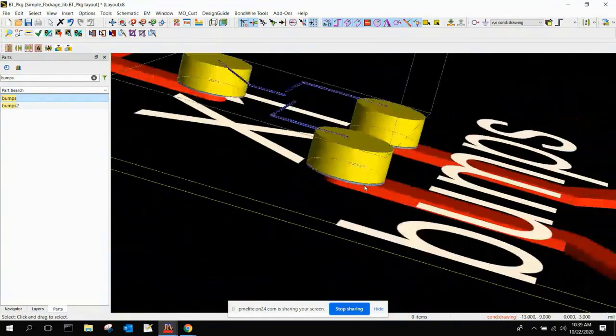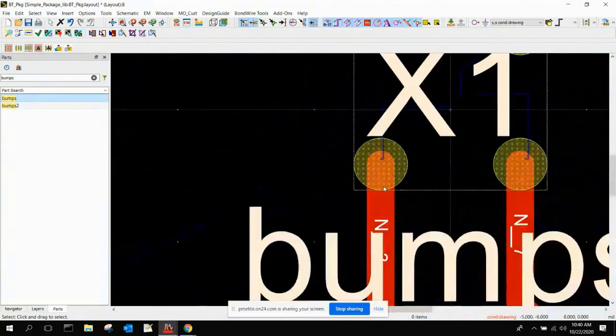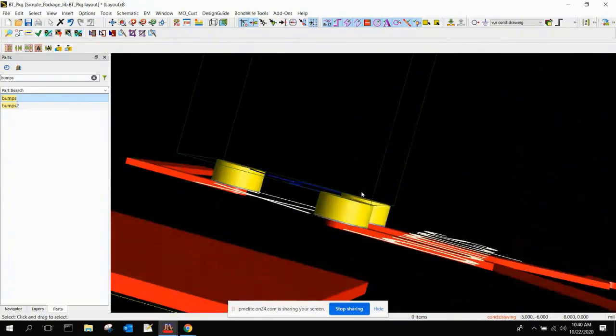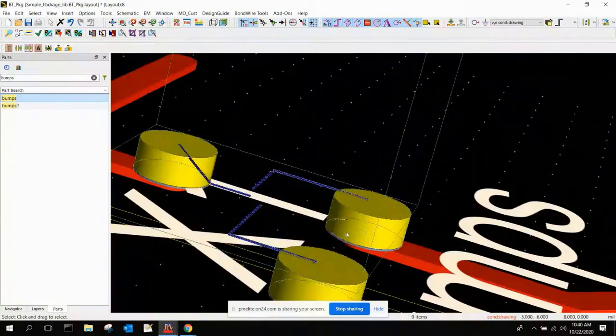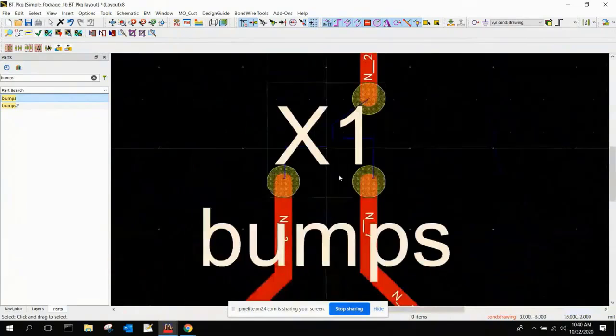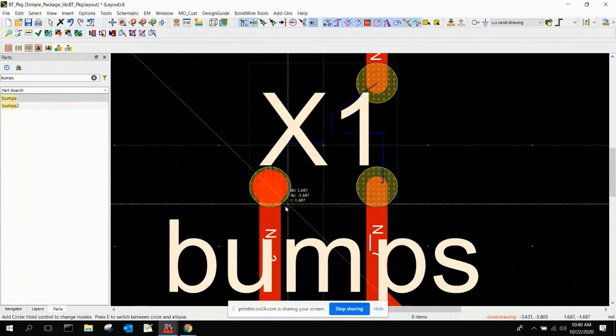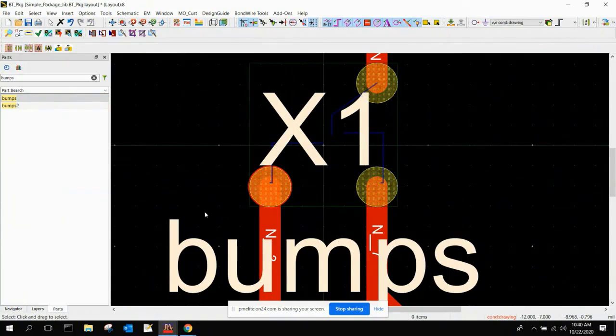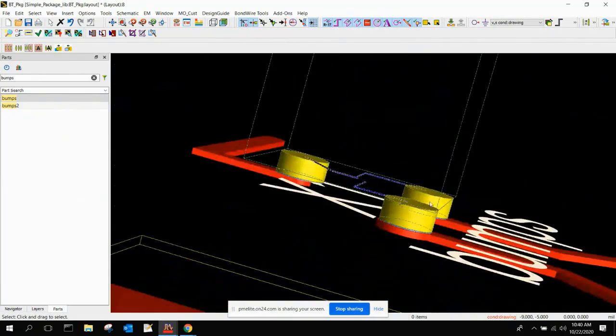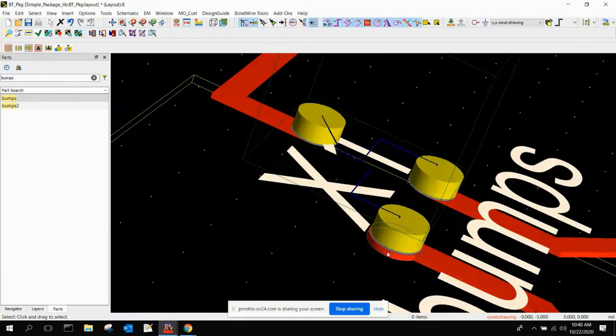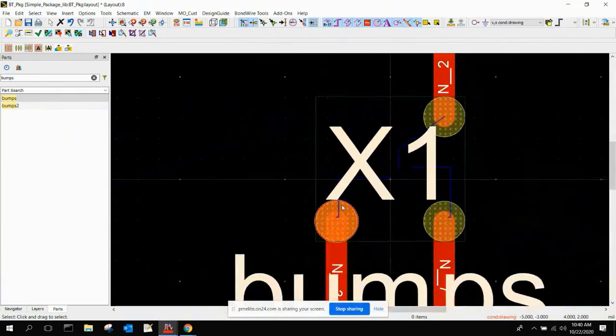One of the things that is a challenge, let's say I'm going to put this onto some traces. I want to make connections to it. Normally, if you drop a chip like this onto a package, you want to have metallization on the package. You need landing pads, of course, for the solder balls to connect to. So something like this really isn't going to work for that case. What I'm saying is I'd really want to take like a circle here, and I'd want to have some kind of a land pad there. That way, I don't want to toggle too much between 2D and 3D, but I want something for this chip to land on. Otherwise, that's not going to work. So it may be complicated. A lot of times if you're designing a packaging technology, if you're starting to assemble pieces of a packaging technology, you have a chip, you're building a package, you don't have all these land pads really vetted out yet.